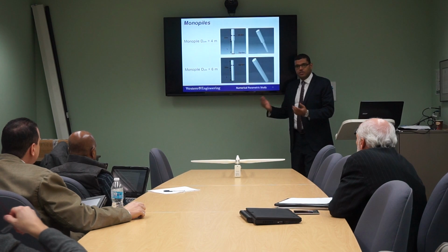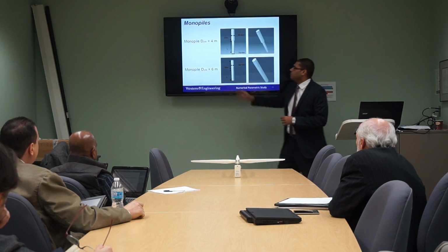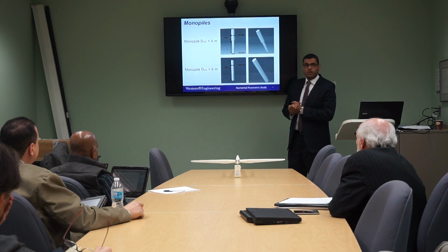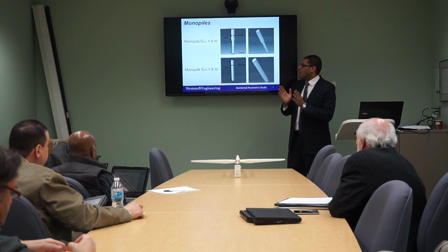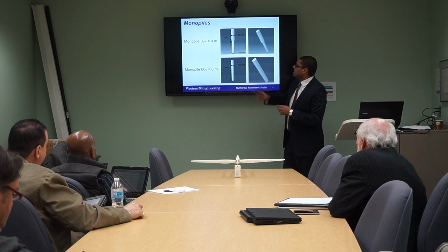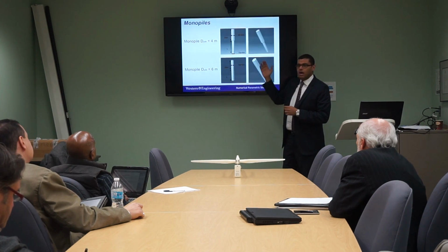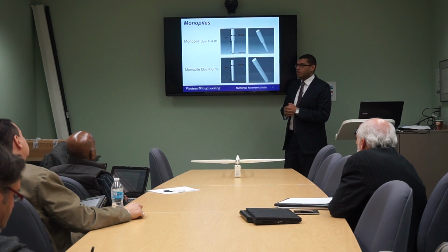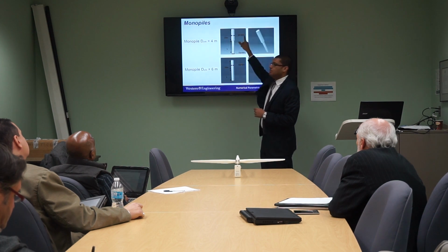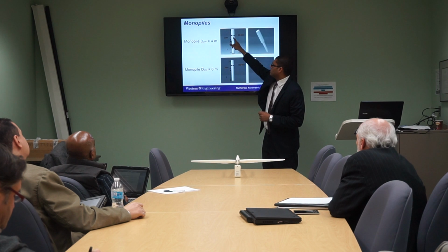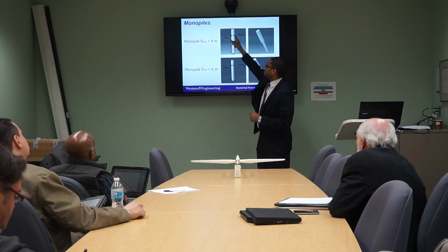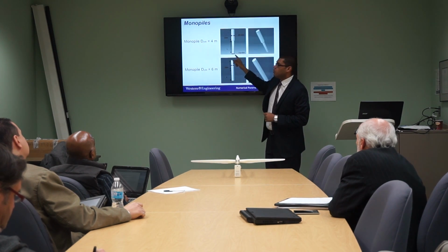We need to present several foundation systems. The first one will be the monopile, which will be a reference pile for us, with diameter 4 meters, which has already been used by the Horns Rev wind farm. But in order to be able to scale and to compare each system with each other, we added this part, which will be 6 meter diameter, to be able to support the other part, and it's the same, to have the same inertia. So this part will be 6 meter, this part will be the monopile with 4 meter diameter.